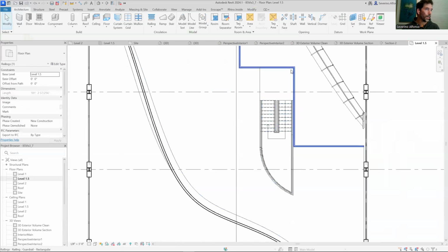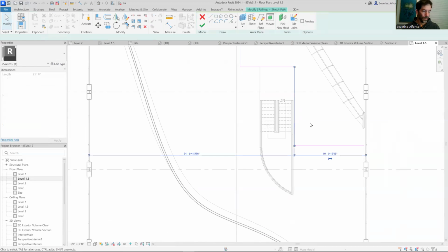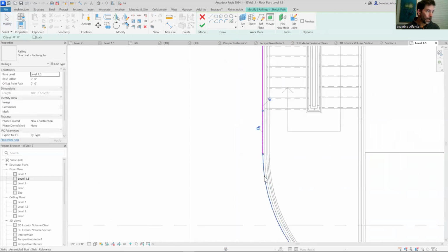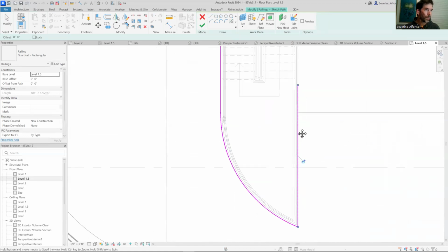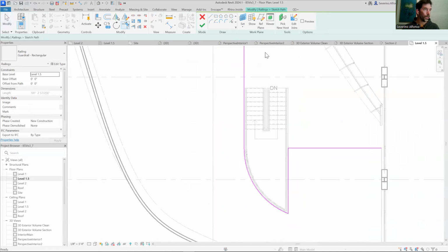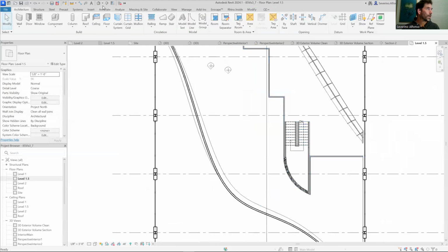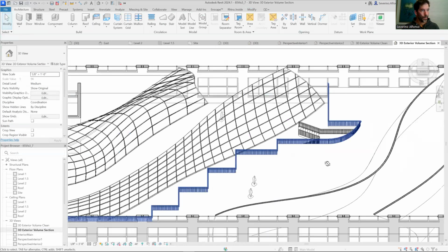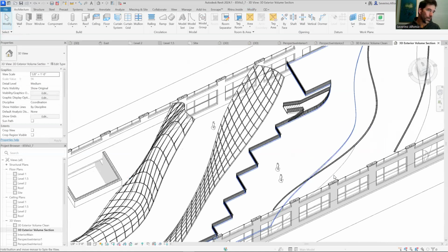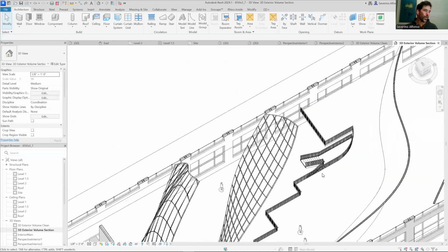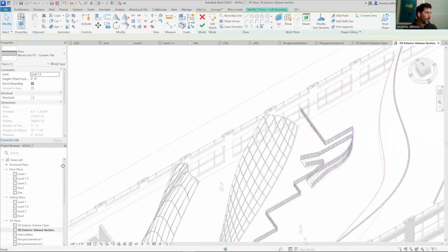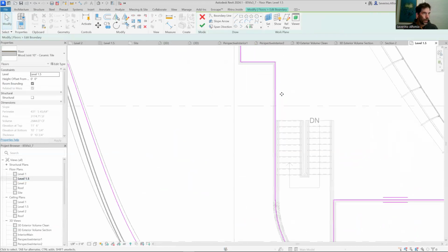And I could leave even the railing, but typically you could just edit the path, delete those, pick the remaining railings here and be located in the top, and TR to make sure it's a continuous polyline. Okay, so let's see how that looks. Well, really, it's a problem here, as you can imagine. So it's not going to work if you're coming up and go to that point. So I could just flip this thing somehow, but I'm going to just continue that, go to level 1.5 and create this.